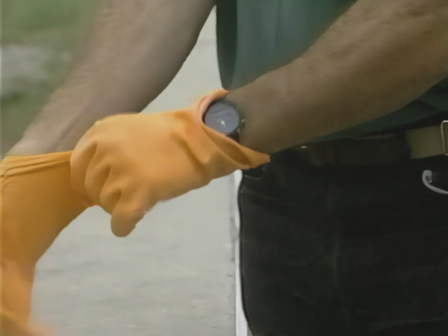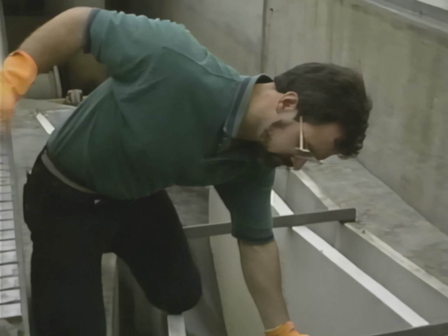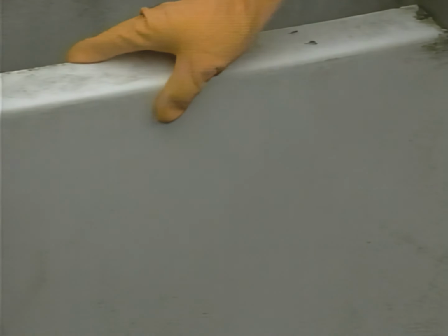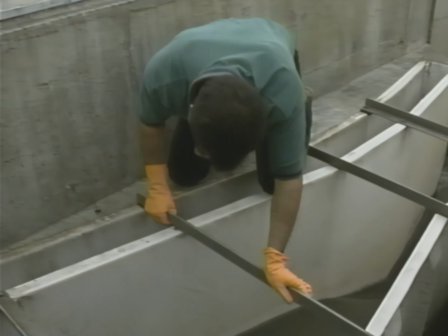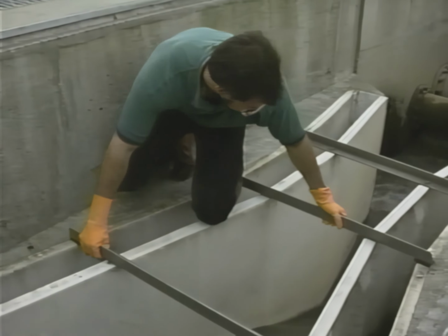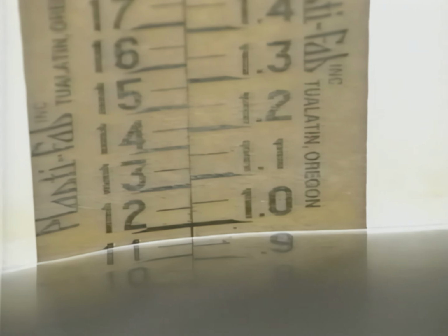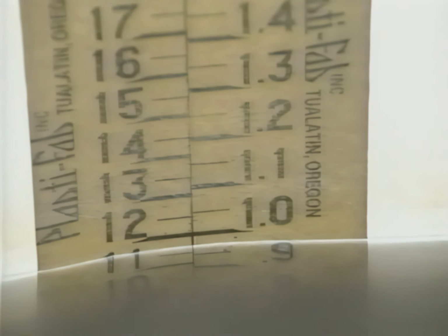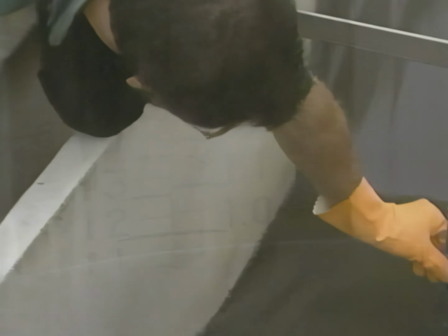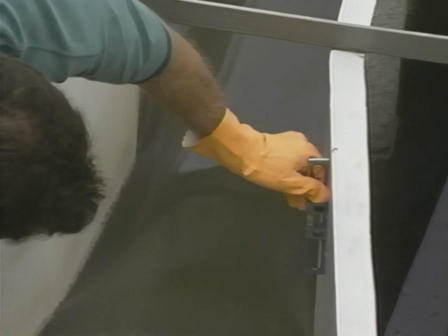Next, check the integrity of the construction materials. Are they still in good condition? The flume we're inspecting is fiberglass, but some Parshall flumes are metal, some plastic, and some are made of concrete. It doesn't really matter what's used to build it, as long as the materials are corrosion resistant and smooth finished to maintain a solid, watertight foundation that maintains measurement accuracy. The flume should also be symmetrical. Make sure the side walls are smooth and vertical. You can check this with a carpenter's level.